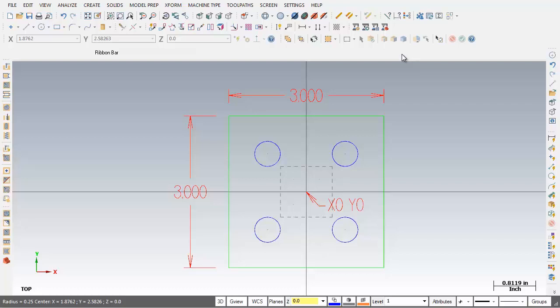So we've created these 4 circles using absolute coordinates to kick off, and then when we undid these last 3 circles, we recreated them using relative coordinates, where we input the distance between centers. Now that completes this video.